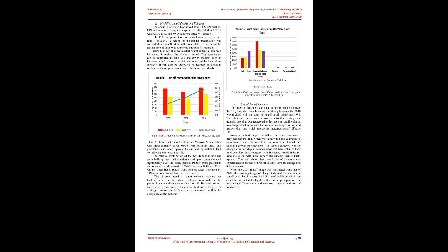Figure 6. In the curve number map for 2018, CN value 86 and CN value 98 were observed as the most dominant CN values. The observation was attributed to 42.5% coverage of the watershed by grasslands and open spaces, which have a CN value of 86, and 37% coverage of the watershed by built-up areas whose curve number value is 98, Figure 6. Fig. 6, curve number maps for the study area in 1989, 2004 and 2018.